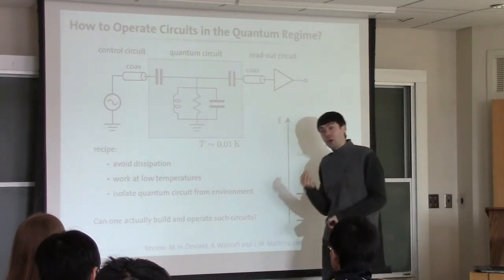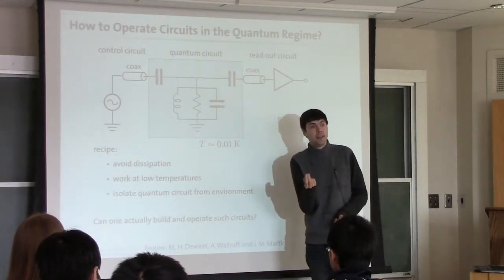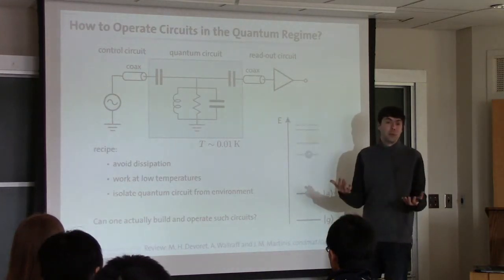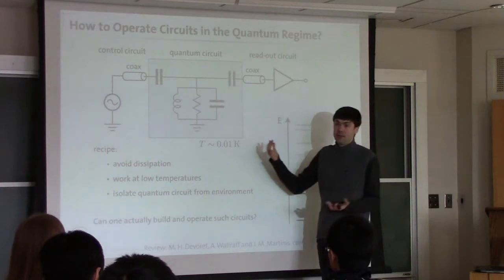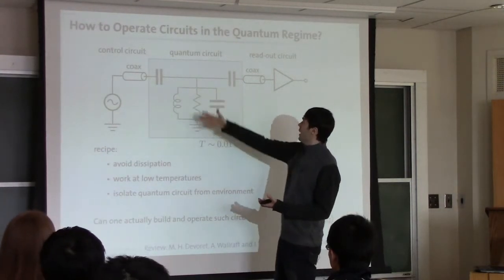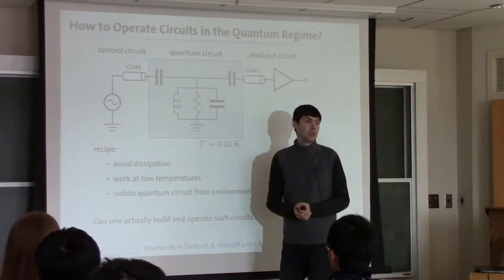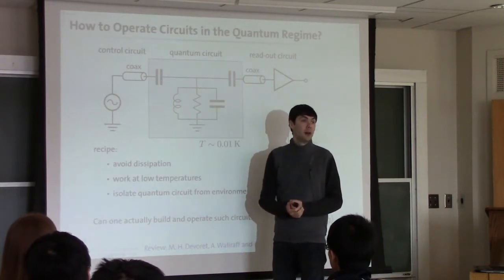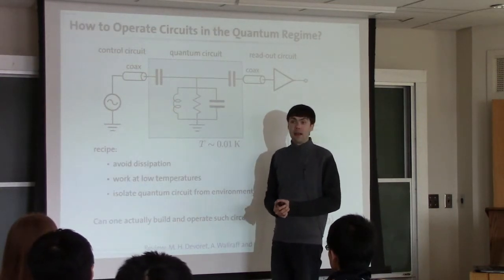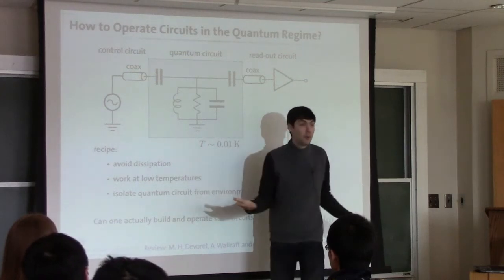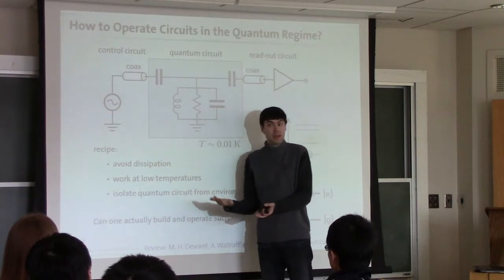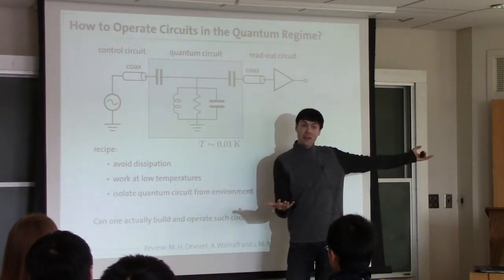But also, because this is an electrical circuit, not only can this circuit be excited by temperature, but also by any signal that comes and couples to this circuit. For example, noise from the environment, any AC fields from your cell phone, from an elevator moving somewhere in the building, from cars driving down the streets.